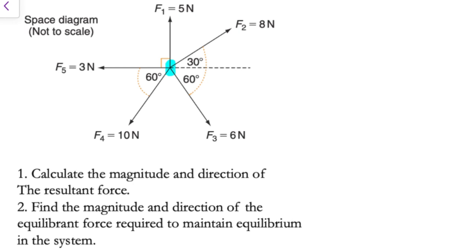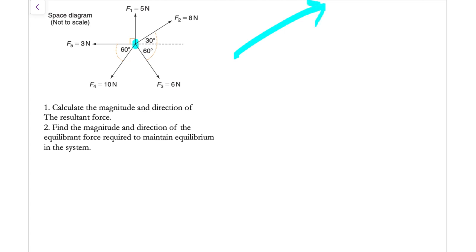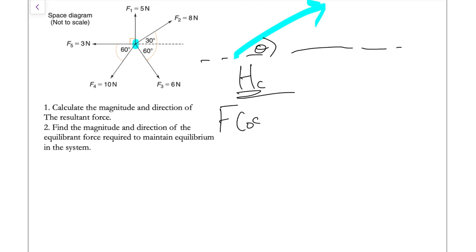Now, the first step is for us to be able to understand how to calculate force components. And what that looks like is we'll have two sets of force components. So for example, if we have a force like that going off on a tangent, that force will have two components. And I'm just doing a little dotted line there that will represent our reference horizontal line. So for the horizontal force component, in this case here, that will just simply be force, cos, and the angle, and our force will be given. This will be much clearer when we're doing the question.